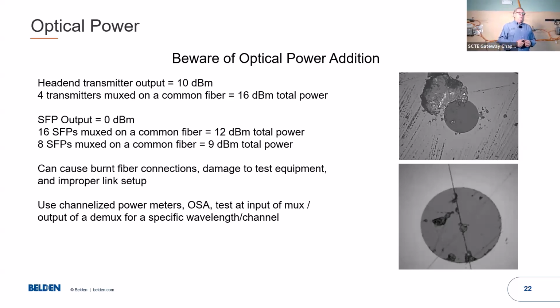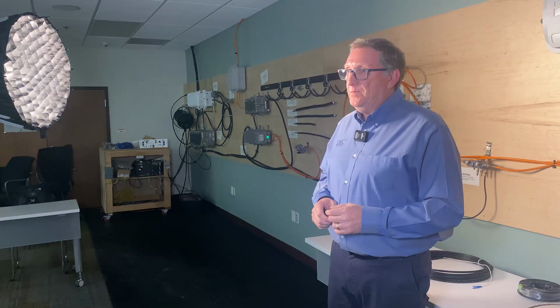We only order single mode optics, which is typically minimum 10-kilometer optics, even if you're going 200 feet. Right. And I have sort of this sense that those data center environments that burn through a lot of optics on a regular basis, but insist they don't want to switch to multi-mode, say we standardize on single mode and it's fine, and they don't pad it down.